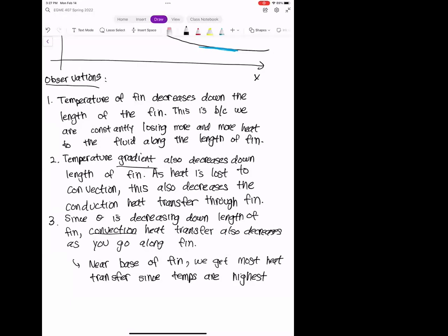And so sometimes you do have to add more length, more surface area, just to achieve your thermal targets. But just know that to make a bigger difference compared to the base of the fin, you have to add that much more length to the end, because the heat transfer is a lot more inefficient at the tips. Any questions on this before we do an example?